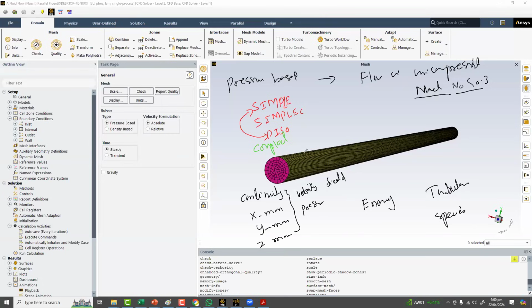So when we want to solve them, the pressure field and the velocity field should satisfy both of them at the same time. When we solve with SIMPLE, SIMPLEC and PISO, what they do is convert them into an equivalent form that contains the pressure terms in the continuity equation. So they solve the momentum equation, and get some pressure field. They put the pressure field into the continuity equation, and if it is satisfied, then it's okay. Otherwise, they go for the loop.